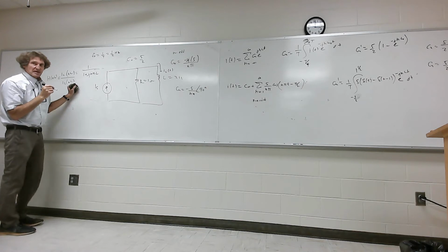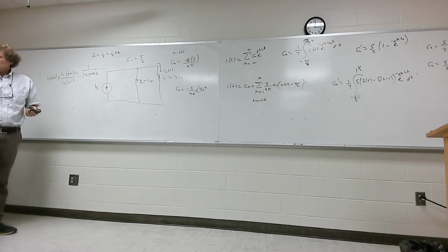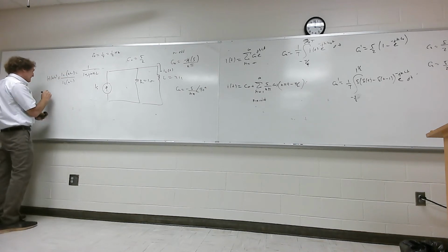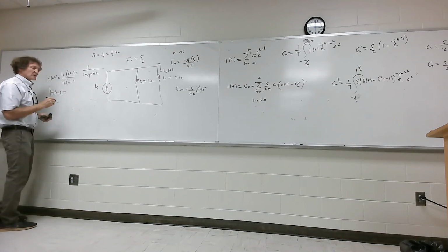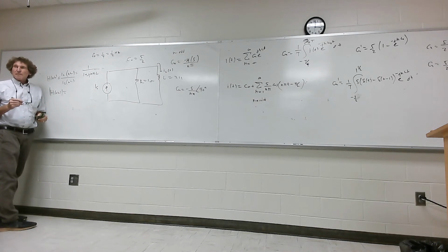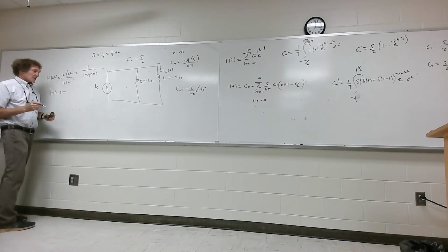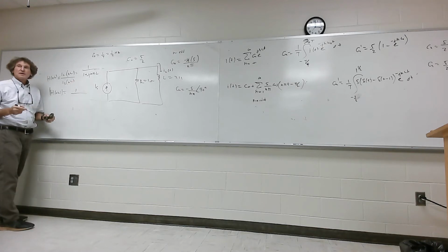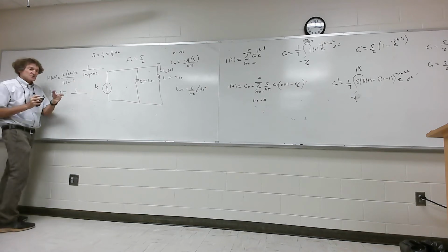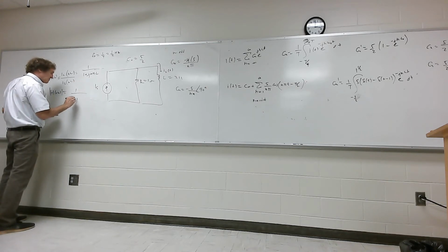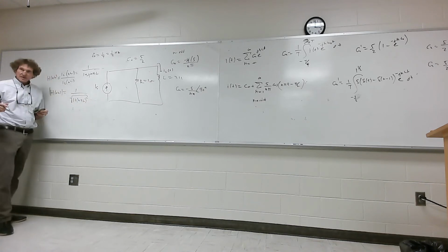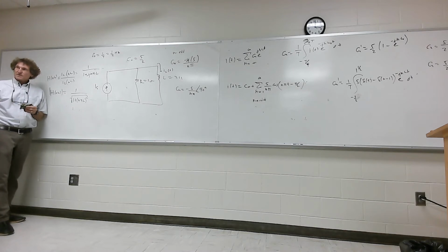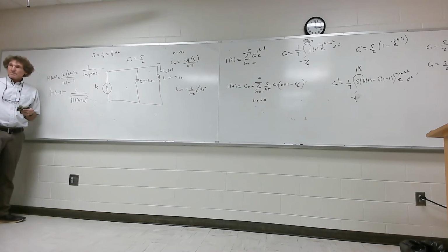That's the transfer function. Now it has a magnitude and a phase, doesn't it, class? If I want the magnitude of H of n omega naught, what's that going to be? Make sure you know how to do this. Top part is just 1. What about down here? Square the values of the real and the imaginary part, take the square root. So this is the square root of 1 plus n pi L squared. And I left it this way for a reason. Correct, class? That's important. Does everybody see it back there?